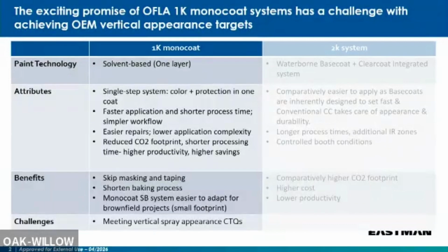So getting back to this overspray application technology, like I told you, 3 years back when we were starting this, there was only one OEM line who had commercialized this. It was a waterborne base coat technology with a conventional clear coat on it. That is the integrated process, the one which you see in the faint corner over here. But today, there are almost 6 lines who are almost commercialized or in the midst of commercializing. Most of them happen to be a waterborne base coat clear coat technology.